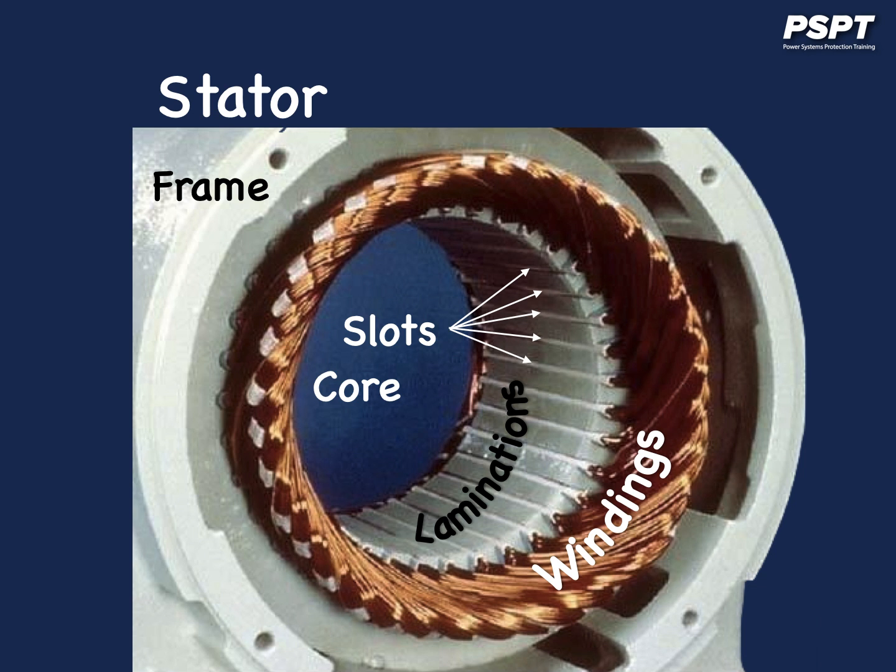The three-phase stator winding is wound for a definite number of poles as per the requirement of speed. The greater the number of poles, the lesser the speed of the motor, and vice versa. When three-phase supply is given to the stator winding, a rotating magnetic field of constant magnitude is produced. This rotating field induces currents in the rotor by electromagnetic induction, the same way that it was done with the two-phase induction motor.